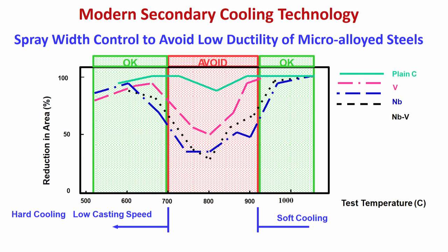So, I have tried to explain how with the help of proper secondary cooling you can have a better quality of cast product. I have told you what the problems are. The problem is secondary cooling should start from the top of the segments, that is at higher segments, just below the mold you should have relatively more cooling, and this should systematically come down, not suddenly. Suddenly coming down, suddenly going up is not good. Uniformly it should come down systematically as you are coming down the segments. That is number 1.